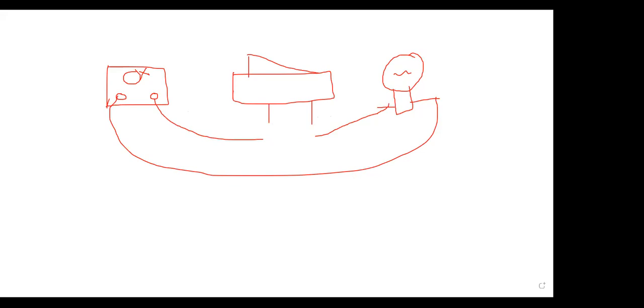As I break one wire, the lamp will be off. So we have to connect our lamp to line and neutral, and we have to break this path. We have to break the line path. In between, we have to connect the switch.